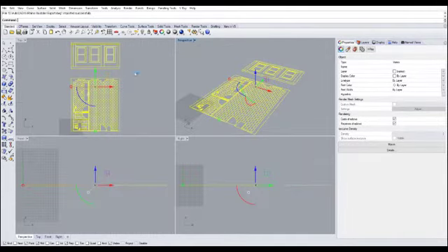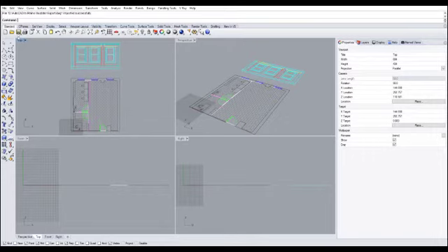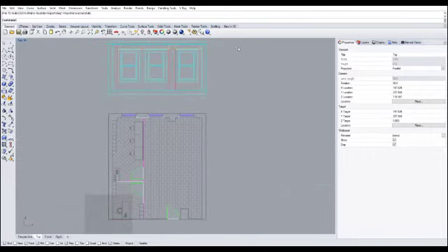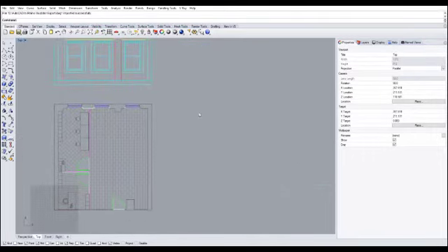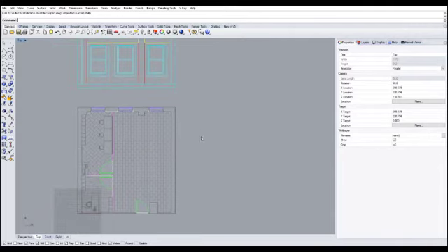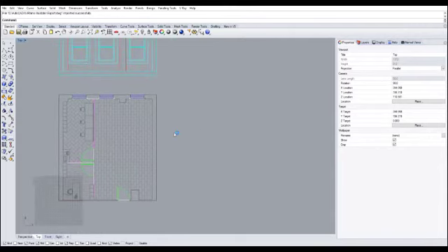And here you have it, the drawings that you were looking at from the AutoCAD section. Of course, we also have to make sure that the units are indeed proper and correct. So I'm going to type in distance. Now I've already said before that Rhino also has an OSNAP setting, which is critical when you're making drawings in Rhino. The OSNAP setting is down here by the menu at the bottom.